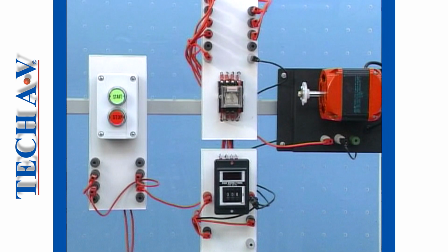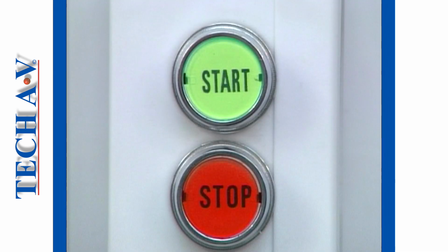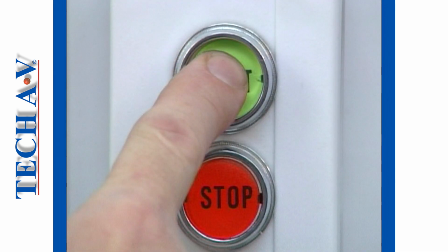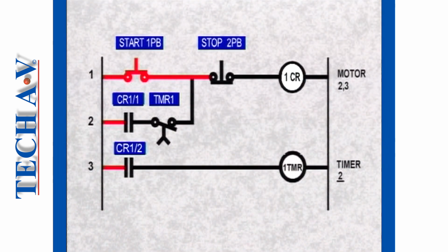Now let's examine the operation of the first 2 rungs using this simple model to simulate the control circuit. The cycle begins when the operator presses the start switch. The switch contacts immediately change from their inactive state to their active state, and since they are normally open contacts, they will close and pass power.